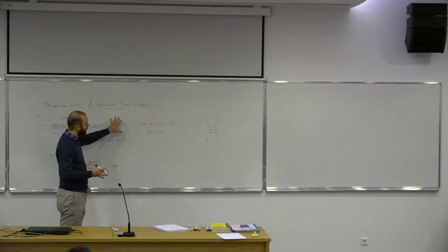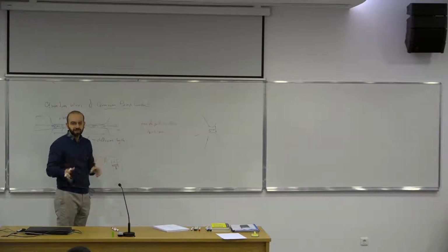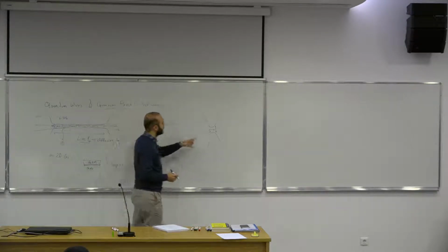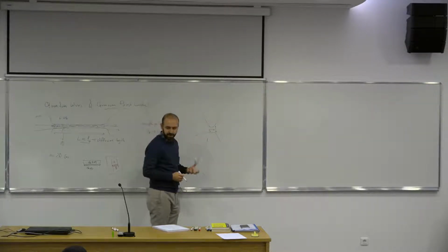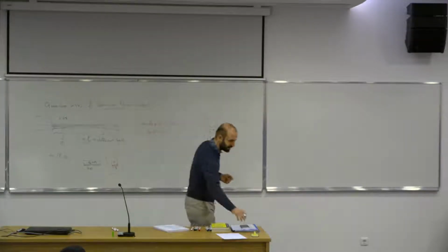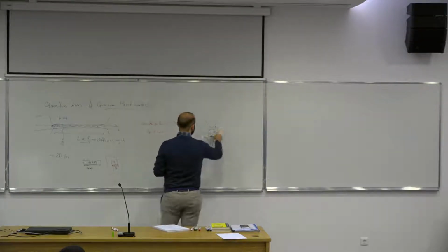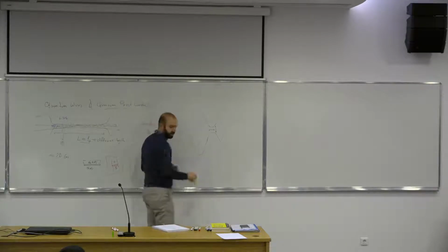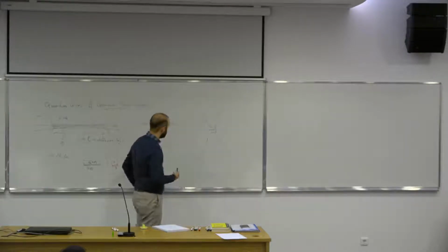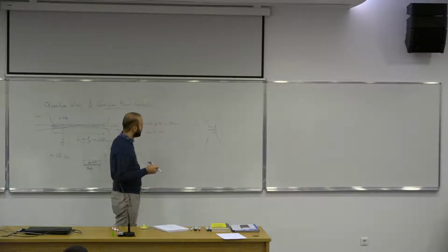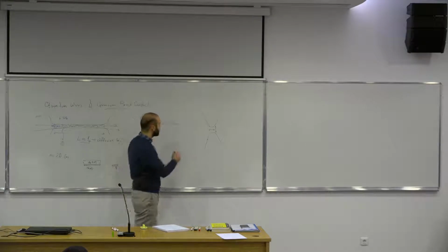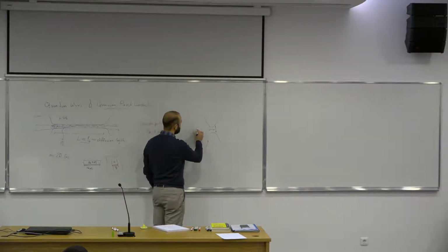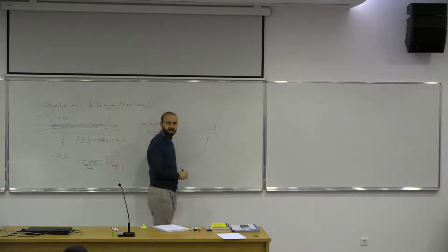So in the overall picture, what we look at is the average motion of the electrons. We never looked at how an electron would go through such a constriction. But now we have this constriction, and we are talking about electrons with Fermi wavelengths that are comparable to the sizes of this object. So what we will see, I'll also try to show you this in detail, but now we have to consider electrons as waves, okay, coming into this channel.